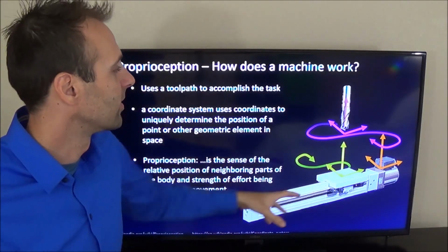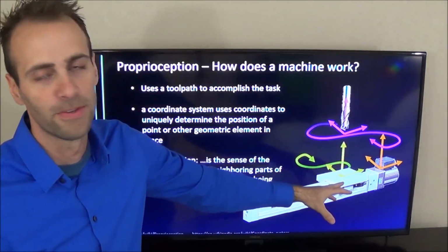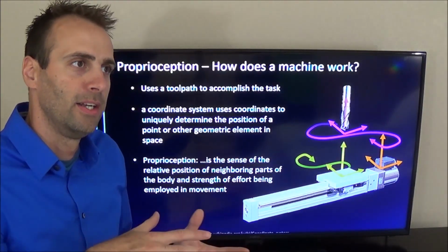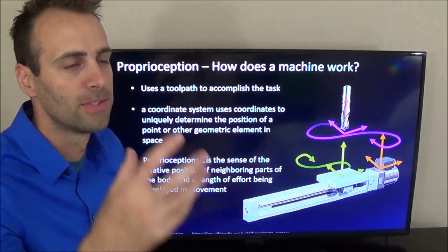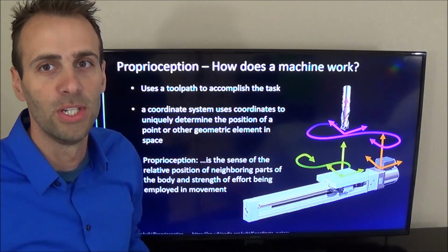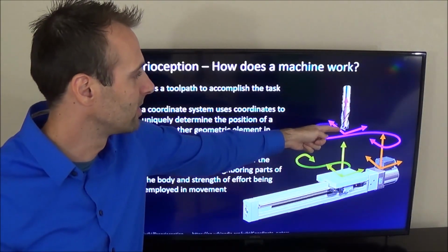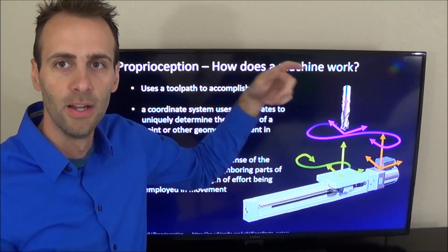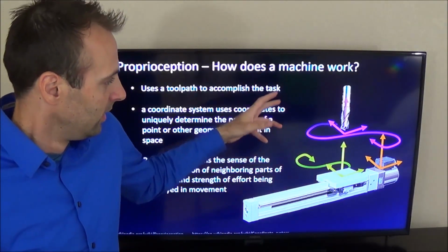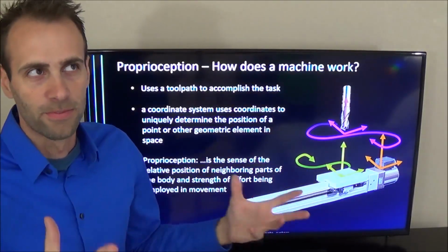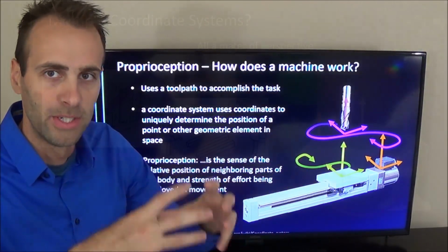That's really all it means. So we're going to keep track of all these different components and what it takes to get them to solve some particular, what we call machine pose, that serves the purpose of aligning the tool and the part with some specific orientation. And that's kind of the gist of what's going on within your machine tool.